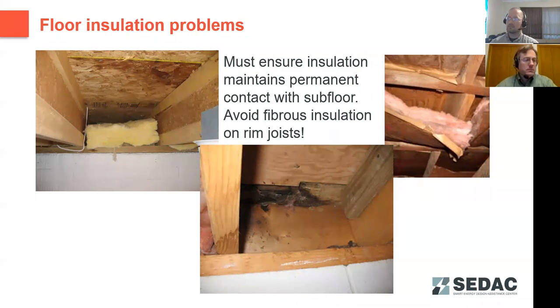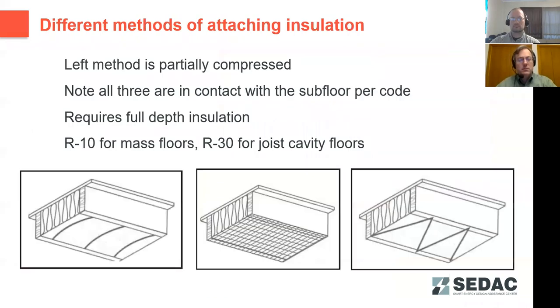Another thing, floor insulation must be pressed up and maintain contact with the subfloor. If it pulls away, you're not getting the insulation value, and so you're not going to achieve compliance. Some ways to hold that insulation up against your floor deck. Commonly see wire ties pressed up between the floor joists to pinch that insulation up in place.